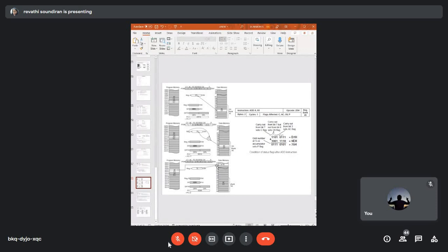That is given here. Now you have to understand that this move instruction, which is in direct addressing mode, holds 2 bytes of instruction. For your move it is F5, and for the address it is holding 1 memory location. So it's a 2-byte instruction, and your program counter will be incremented by 2. Now you have 30: in location 30, the result in the accumulator is being stored.